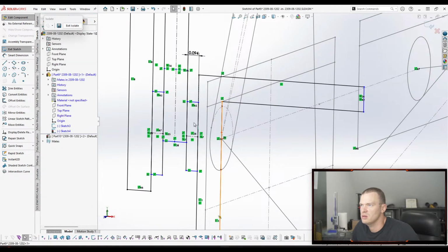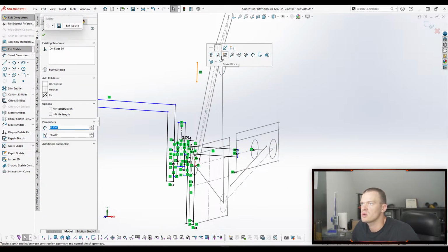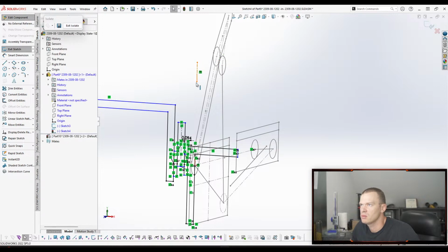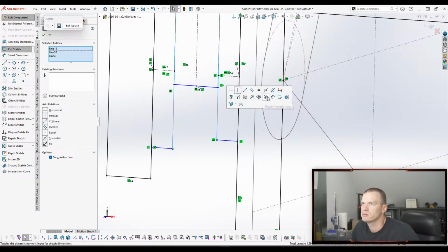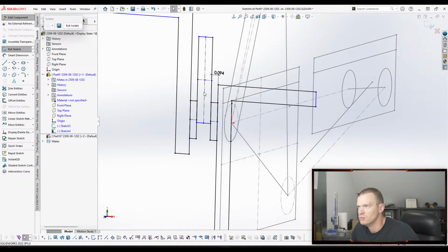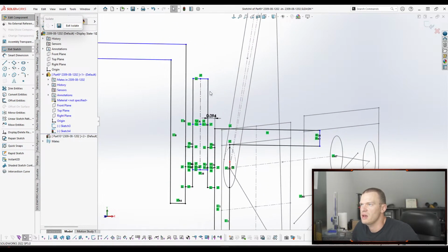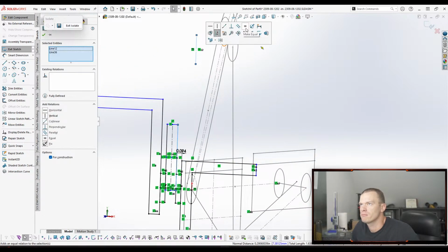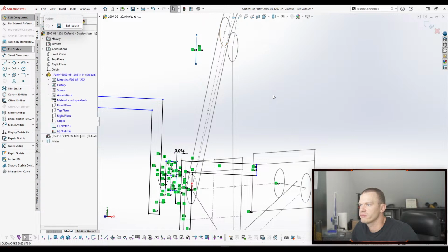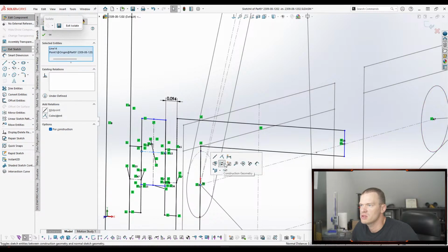So what we can do is maybe we derive in a different one, since we know these all have relationships to each other in a different sketch. So we can just derive in a different one up here. And then make all of these equal. Now it sets that. Now our linkage, we know, is also 1/2 inch in diameter. Or in width, I guess. And we can put this here, that's fine.